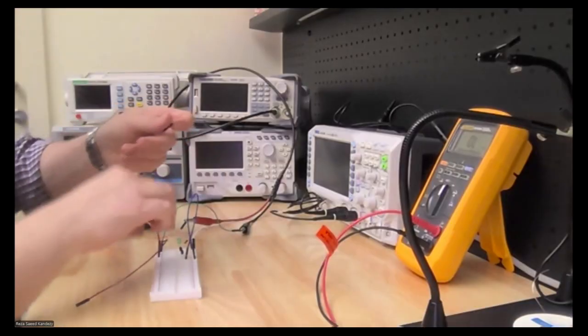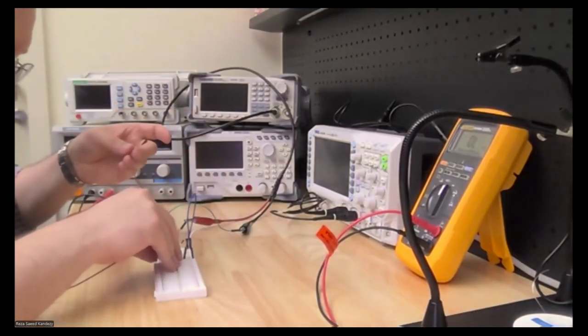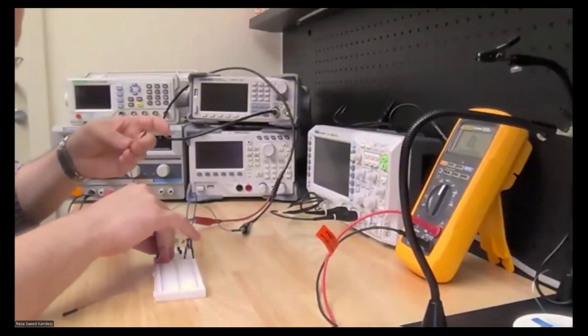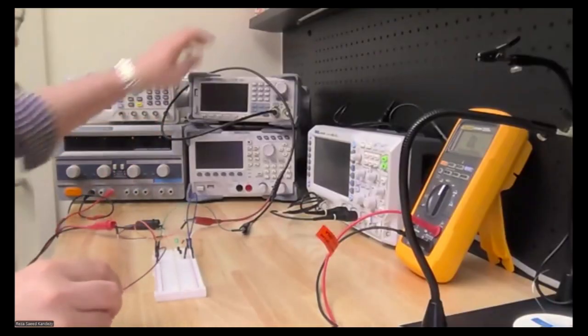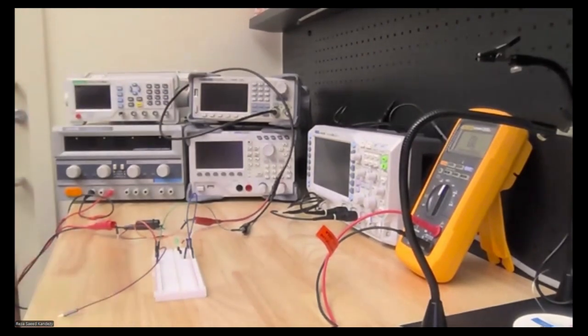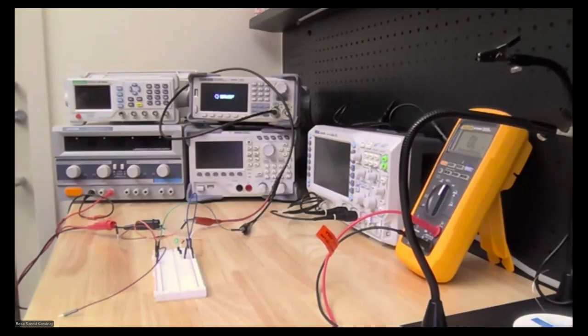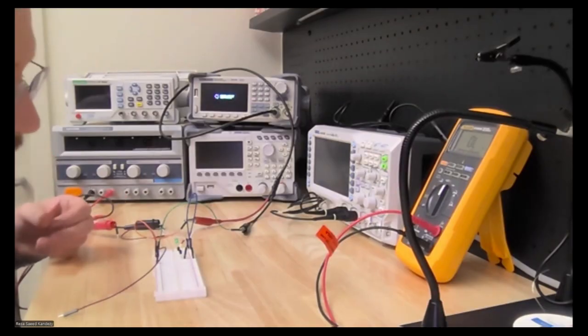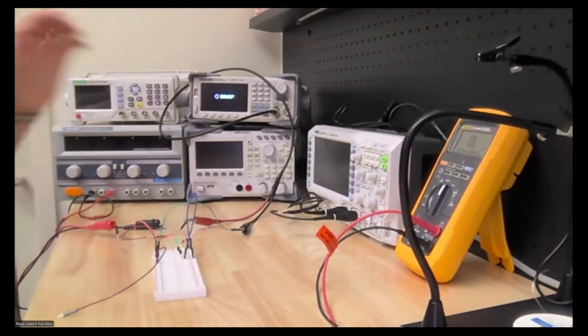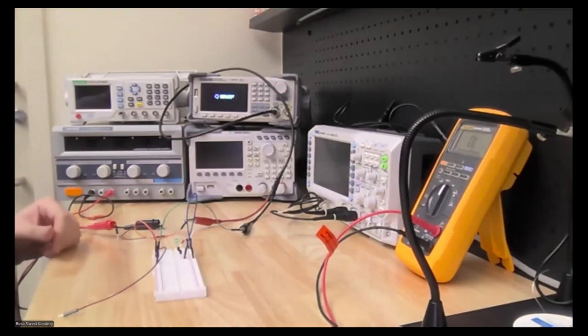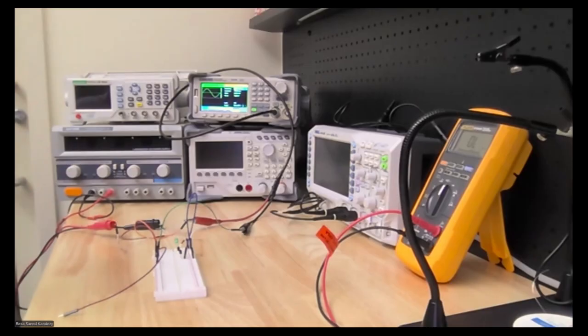Okay, now we are good to go. Before we go, let's set our function generator. I'm gonna use the square wave, but with a high duty ratio, close to 100%. It doesn't give you 100% as we mentioned before. So the maximum is 99.99 that the function generator can have for the duty ratio.